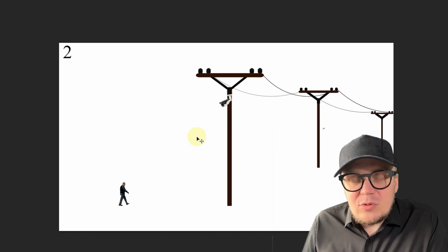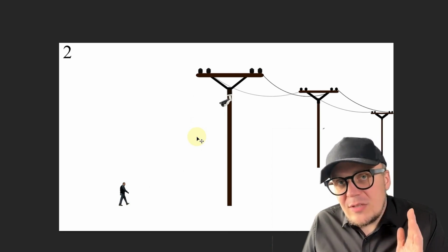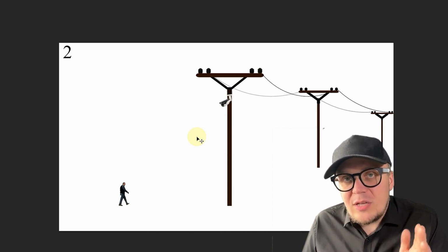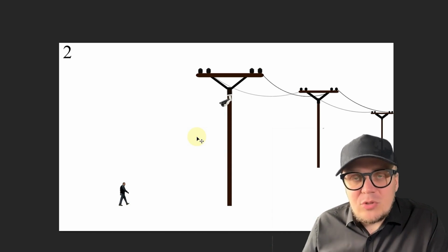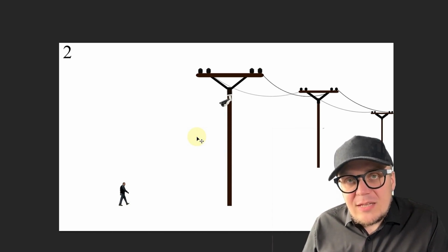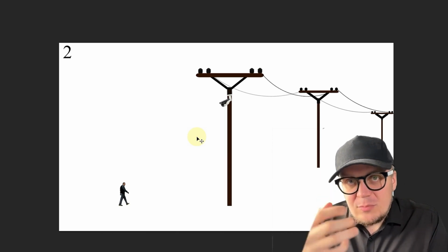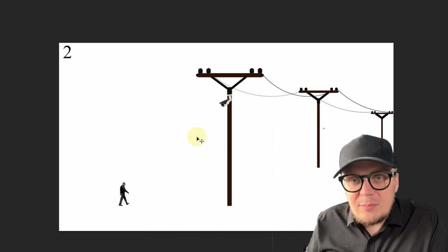The optimal height for installing a surveillance camera is between 3 to 5 meters. I always recommend 3.5 meters. This is more than enough to keep the camera out of reach of vandals. And this height is sufficient to see the facial features of a person even wearing a cap.